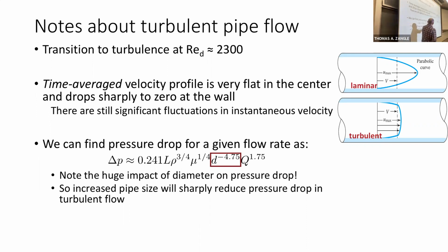So if we have a pressure drop that's too large for a given pump, let's say we're specifying piping that should go into some run within some plant, and the pressure drop that we're computing is too large for the given pump that currently exists at the plant. And you're specifying this in stainless steel or something, so it's really expensive pipe. You might be hesitant to specify a larger pipe diameter because the stainless steel is going to be pretty expensive.